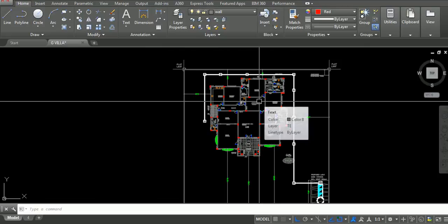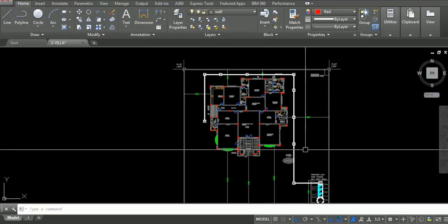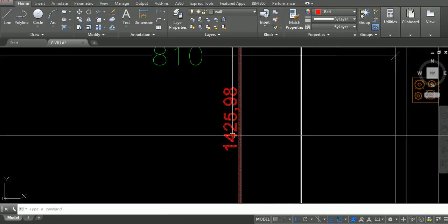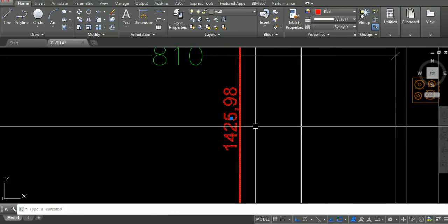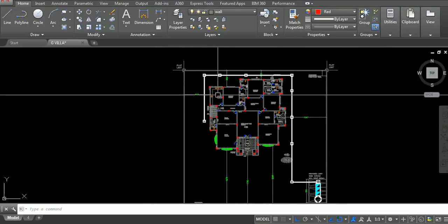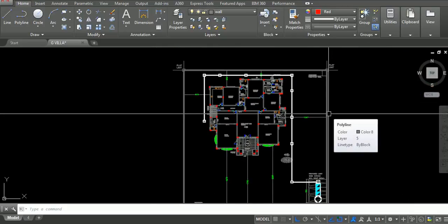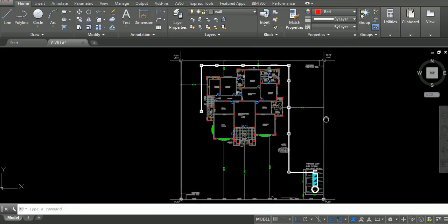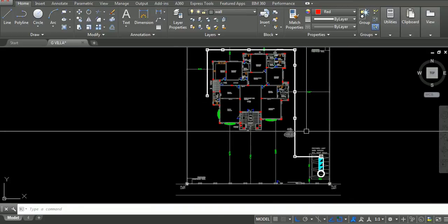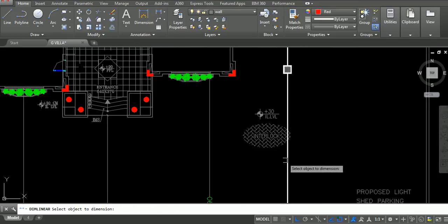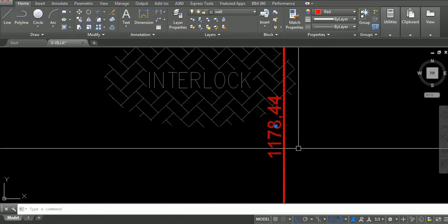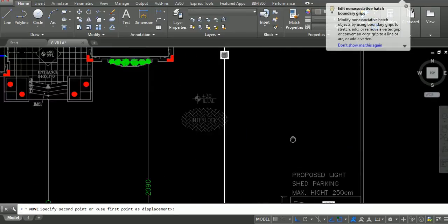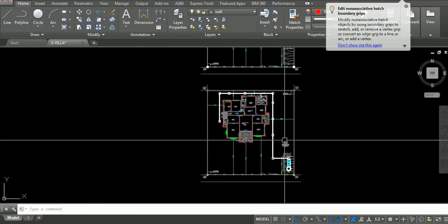Because after starting the design, we will know what's happening. Also the dimensions, to make them a little better, not like 0.89, 0.9. I prefer to make them simple numbers, like 2 meters, 3 meters, 10 meters. And also, of course, there are restrictions. The maximum, like here, is less than 12 meters, but I always prefer to be less than 12. Up to 15 is acceptable here.